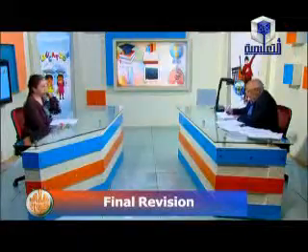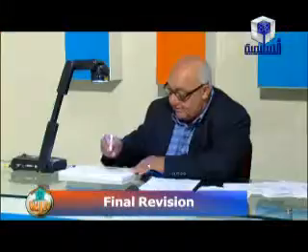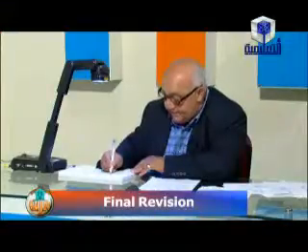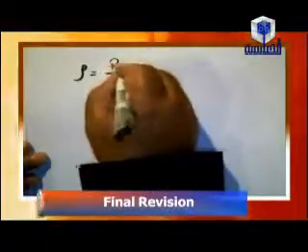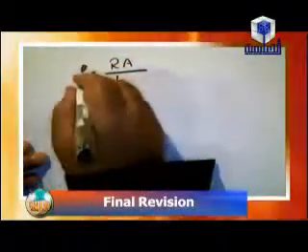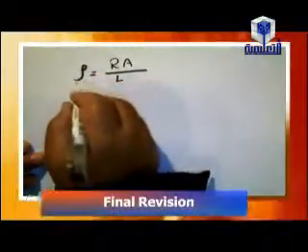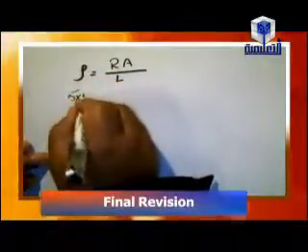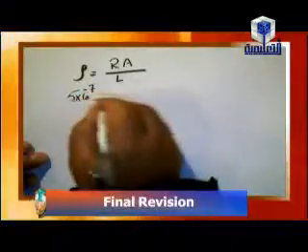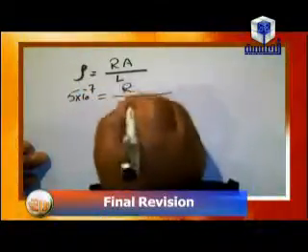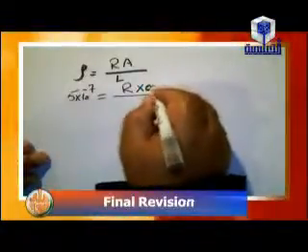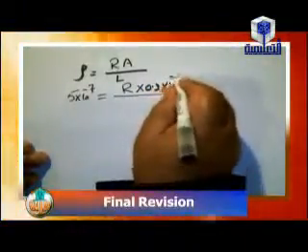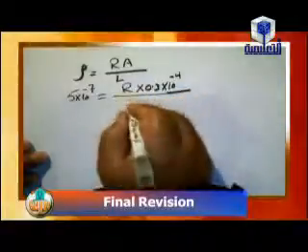So first we must find the resistance of the wire from this law. Rho equals R A over L. Rho, the resistivity, which is equal to 5 times 10 power negative 7, is equal to R unknown times the area, 0.3 times 10 power negative 4, over 30.